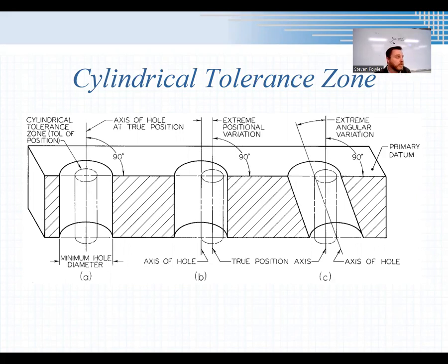If you do this in metal, if you drill through a thicker slab of metal, that metal probably is not going to bend and be very forgiving. So if I need that hole straight in that metal, it's very important that I drill that hole right straight in.